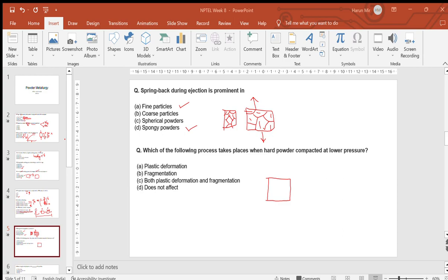You just have to say what is the sequence for a powder injection molding. First, you should know that. Formation of feedstock, molding, binder removal, then sintering. So you are saying this option is right, right? I think the fourth one. Yes, that is right.